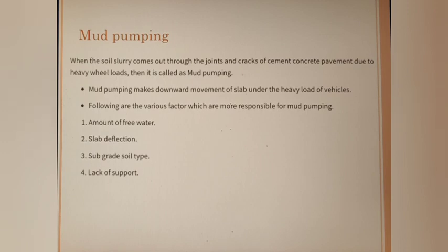So the main reason for mud pumping is a amount of free water under the slab. Second reason is the deflection of the concrete slab. Third reason, that is due to the nature of the subgrade soil. And fourth is due to the lack of support.